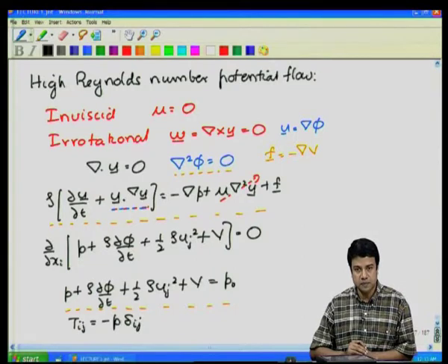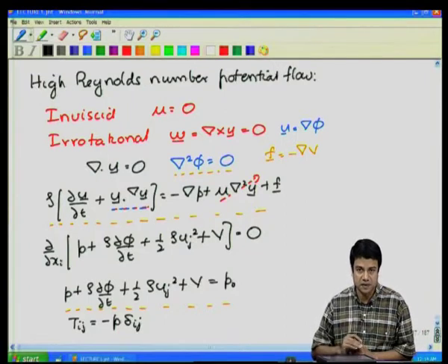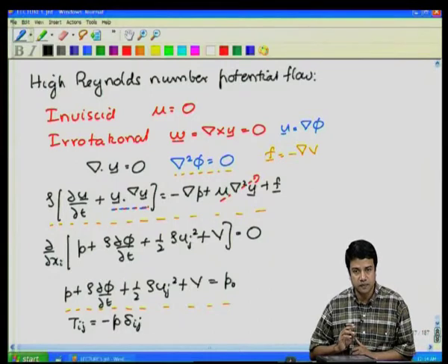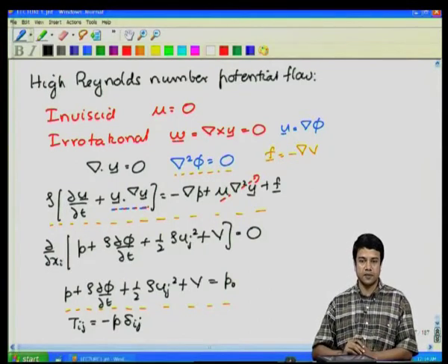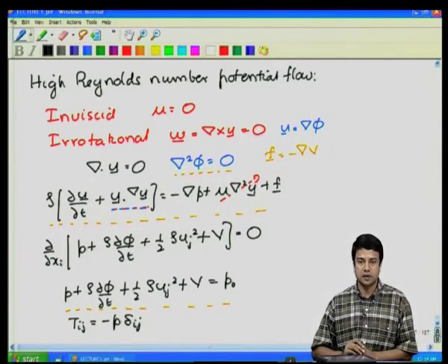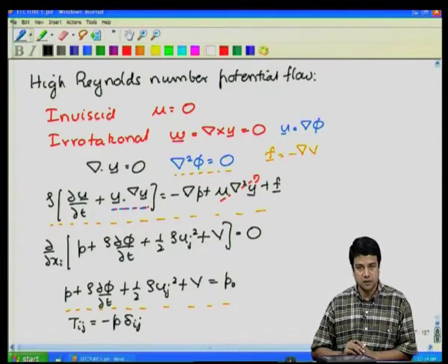The tangential velocity boundary condition, that is, in order for the flow to come to a stop at a stationary surface, you require momentum diffusion from the surface. In our potential flow approximation, we've set the viscous term equal to 0. There is no momentum diffusion. Therefore, the velocity field does not decrease to 0 at the surface.